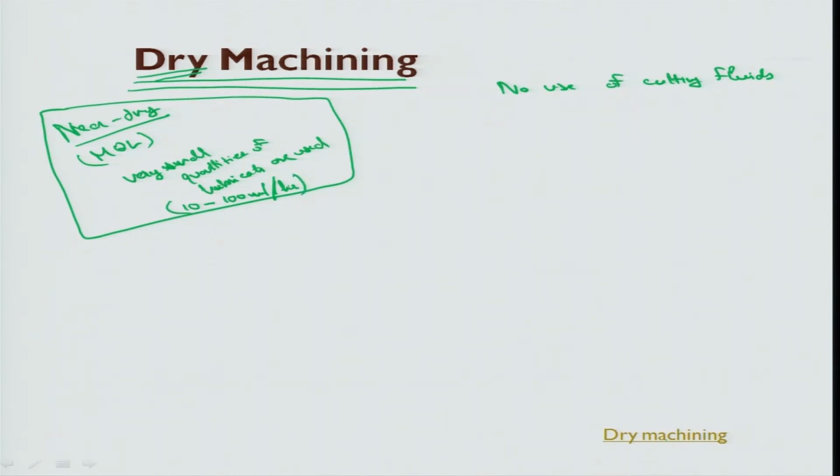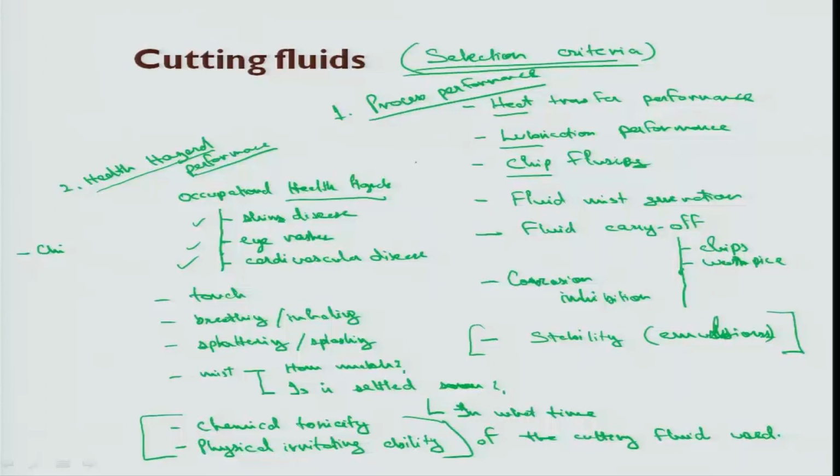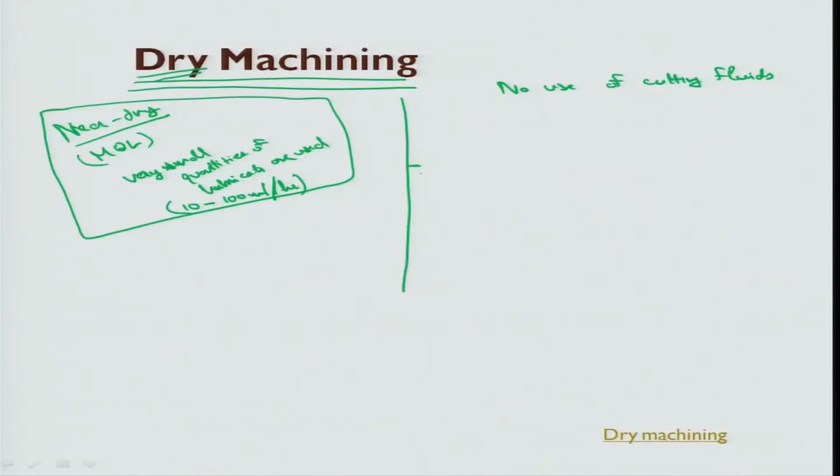So dry cutting is made possible by recent developments, but there are challenges. What about the heat transfer? What about the lubrication? When the heat is very high, the workpiece heat would go to the tool, the tool life would become less, even the heat flows to the workpiece as well, no chip flushing happens, and certain similar problems are associated. That is, heat, where would our heat go?